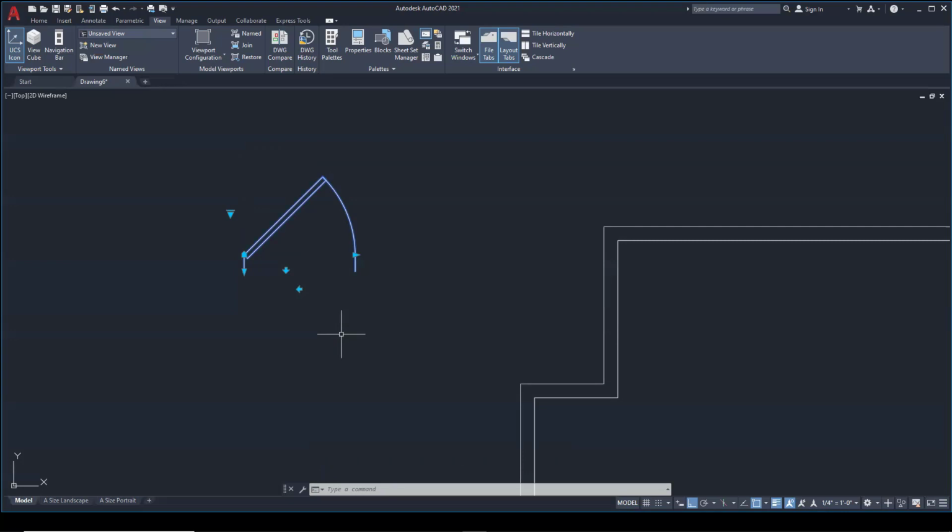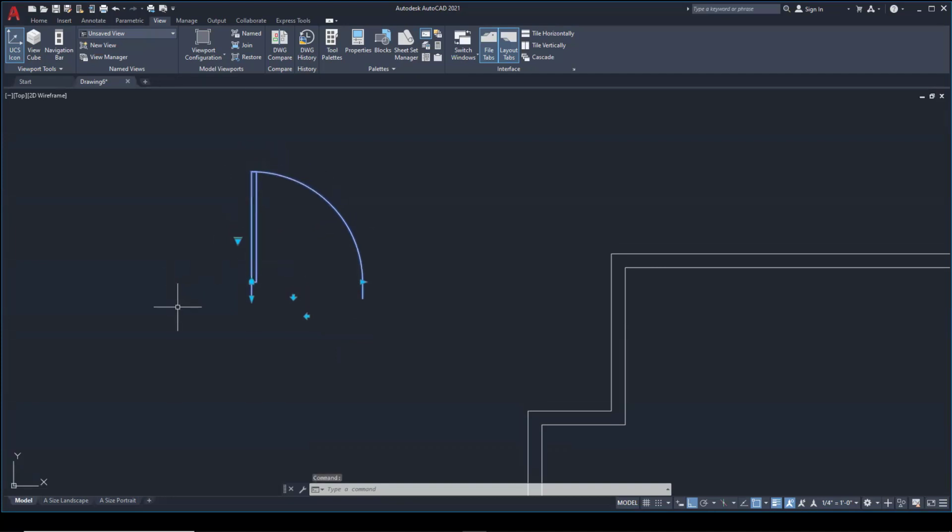But you want to cut a new door or add a new wall with new doors, and maybe you have 2 or 3 new doors in your redesign. You want to show those doors at 90 degrees. So generally, and this isn't always the case, new doors are shown at 90 degrees, and sometimes existing doors are shown at 45 degrees. For the sake of argument, we're going to put all of our doors at 90 degrees.